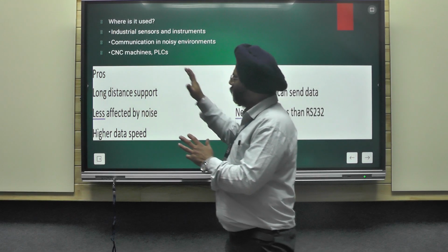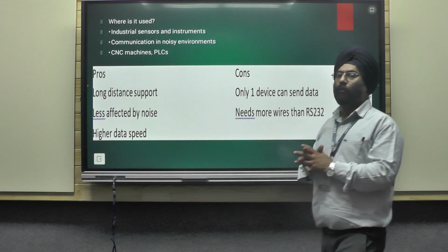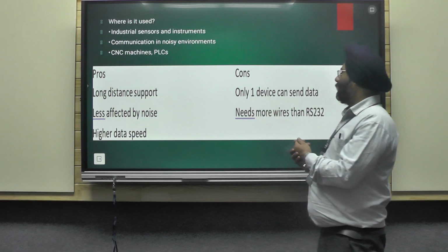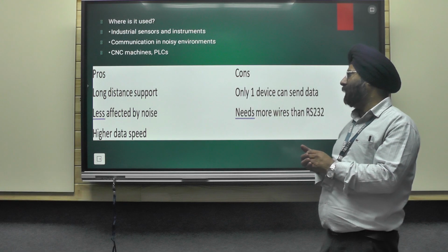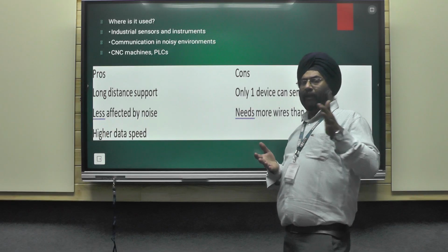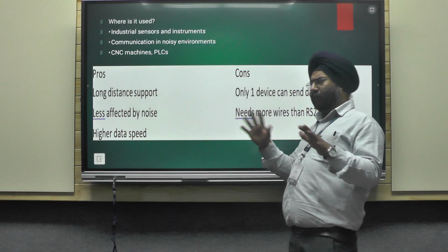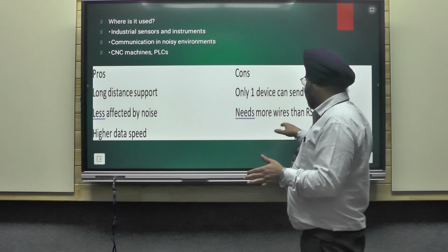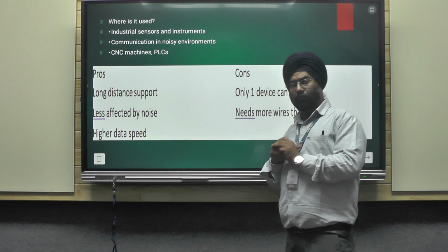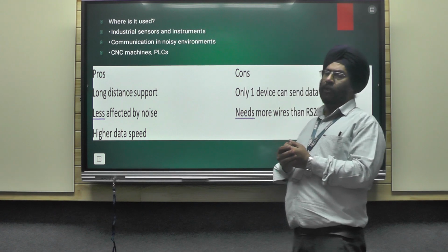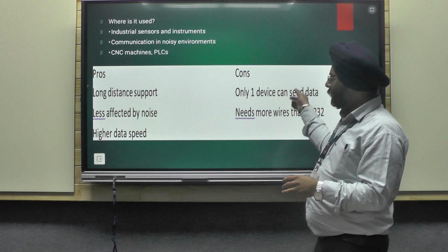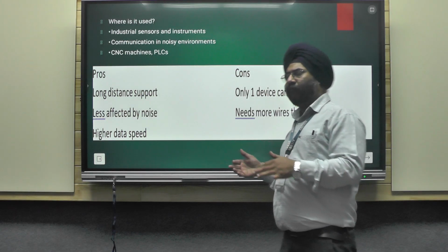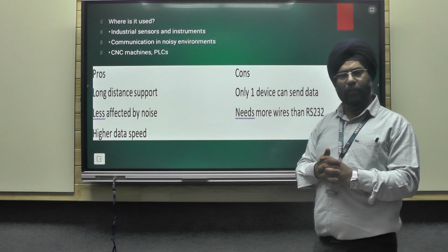It is appropriate there, and there are cons, a negative part is also there. Only one device can send data at one time, because there is one sender and many receivers, but communication at one time is one sender to one receiver. It needs more wires than RS232. In the RS232, there were only 3 wires. In the second one, there are 4 wires. So these are the cons that we are looking at in the RS422 standard.